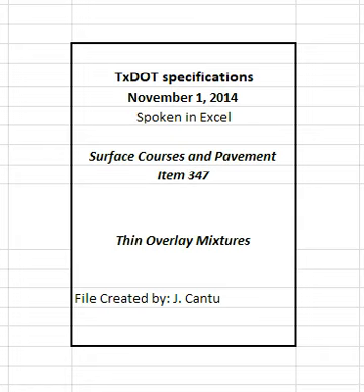4.4.2.1.3 Submitting JMF1. Furnish a mix design report, JMF1, with representative samples of all component materials and request approval to produce the trial batch. Provide approximately 25 pounds of the design mixture if opting to have the department perform the Hamburg wheel test on the laboratory mixture, and request that the department perform the test. Provide approximately 50 pounds of the design mixture to perform the overlay test.